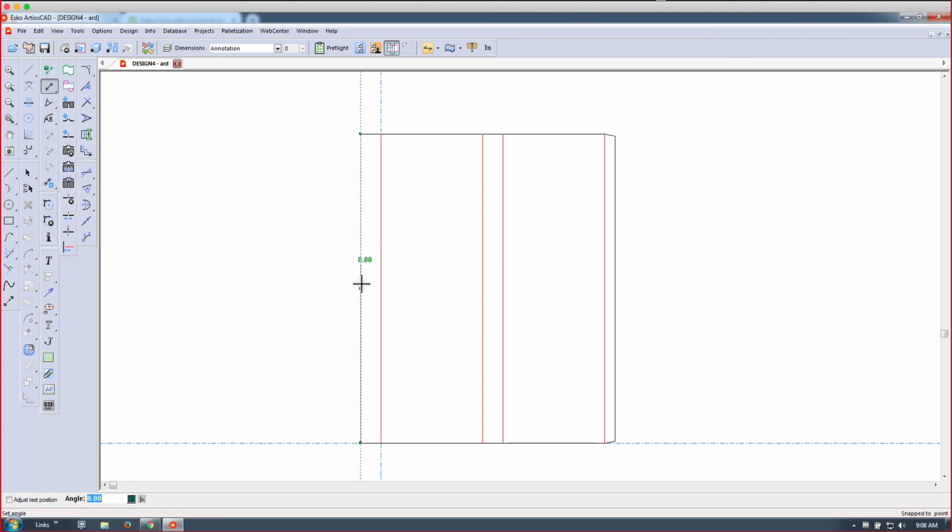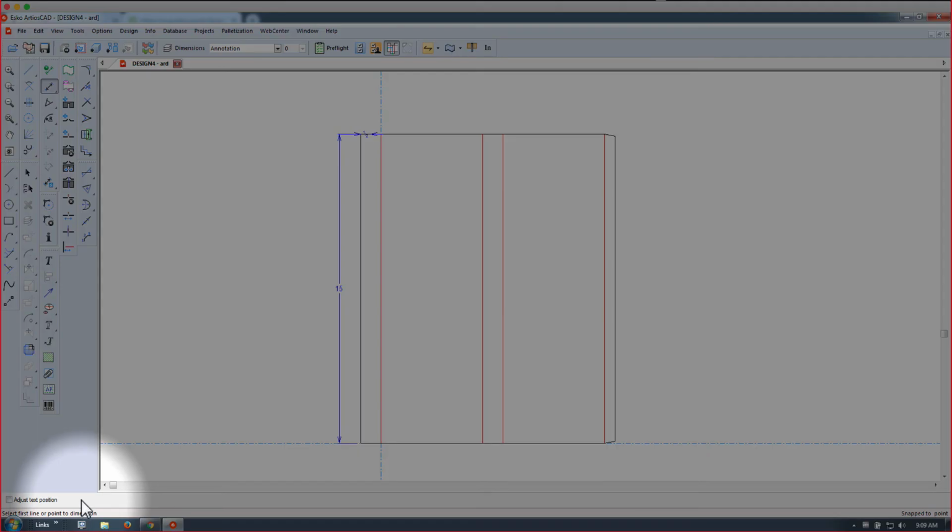One click here, followed by an angle, followed by a second click right here, and then pulling out, I can now position that line like so. So again, one click indicating my angle as 0 degrees, second click, and then pull out. So you'll get used to that. Also, always keep an eye on the information here in the lower left-hand corner.